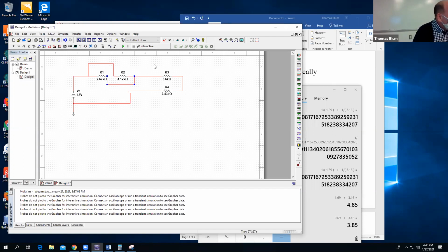Parallel in electronics class is about how you're connected. Series in electronics class is about how you are connected. Series means that you see the same current. It's got no place else to go. Parallel means there's a connection of wire on one side and a connection of wire on the other side, which ends up meaning that you see the same voltage.